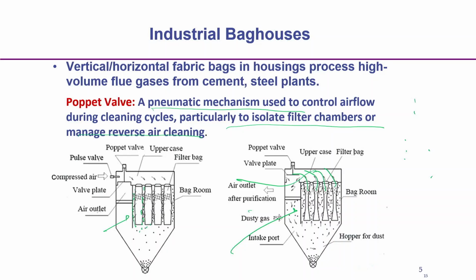So, this loading will enhance the power cost, because it will allow the dusty air to pass through at a certain rate of air flow. The particles, the cake formation, will restrict the motion. So, that pressure drop will increase, which will enhance the power consumption.